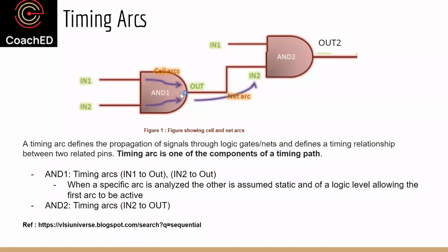But if the circuit is connected in a netlist, meaning connectivity information of various logic gates, so this AND gate is connected to this AND 1 gate, and since this connectivity is there, the information about what is the capacitive load on this pin has to automatically be available when we are running the flow, and therefore this input capacitance is also pre-characterized.